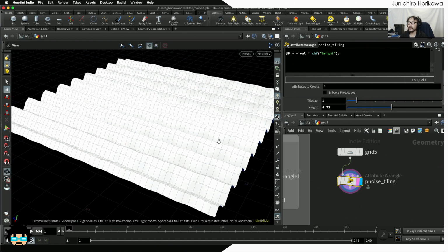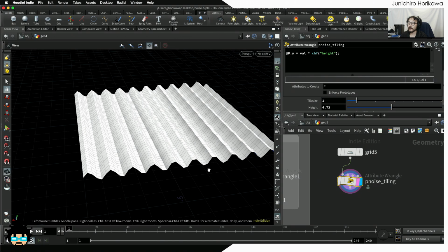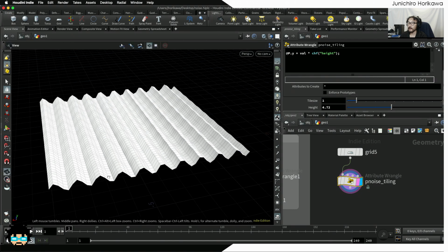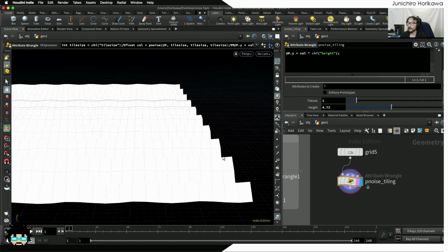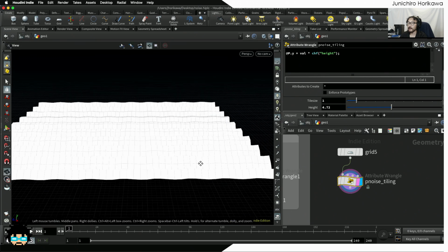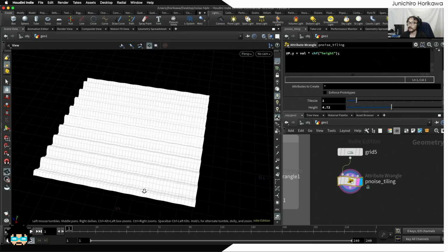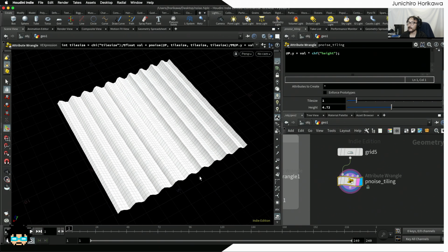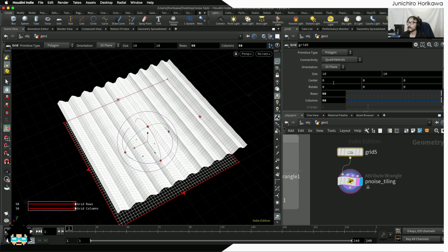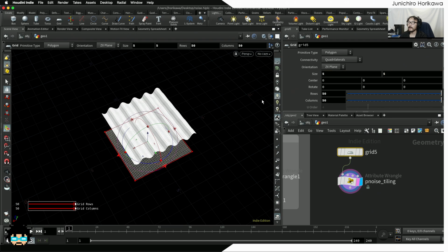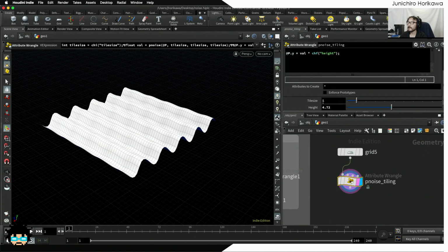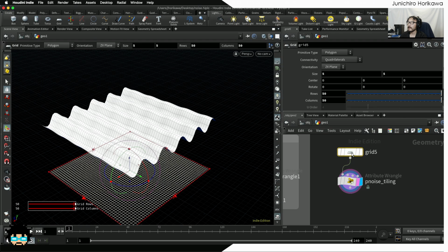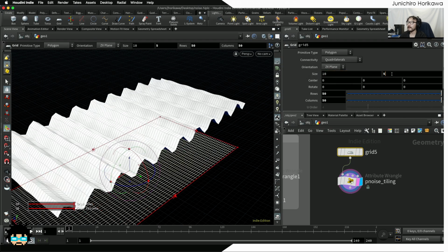you obviously see some repetition happening in the x direction, 10 times, I think. And also, if you look closely at the z direction, there is also some small wave happening, and it's happening 10 times as well in the z direction. And the reason it's 10 times is because the size of this grid is equal to 10. So if I change this to 5 by 5, then the repetition becomes 5 by 5. That is because I am setting the tile size as 1. Okay, so let's make this back to 10 by 10.